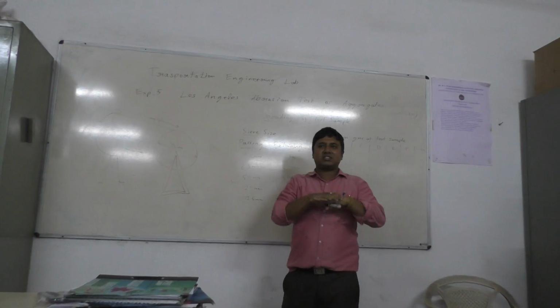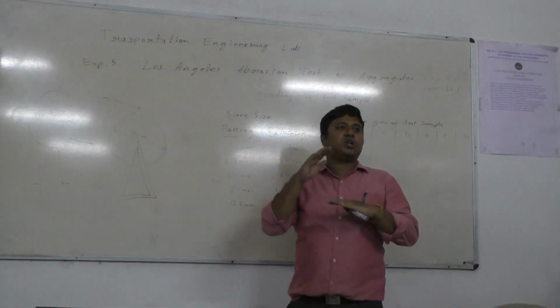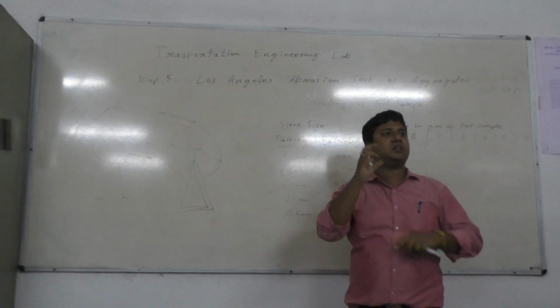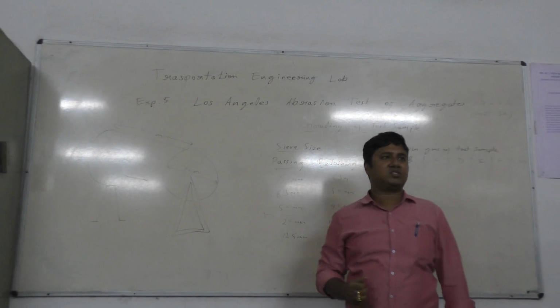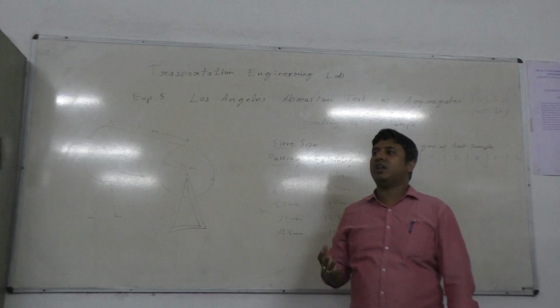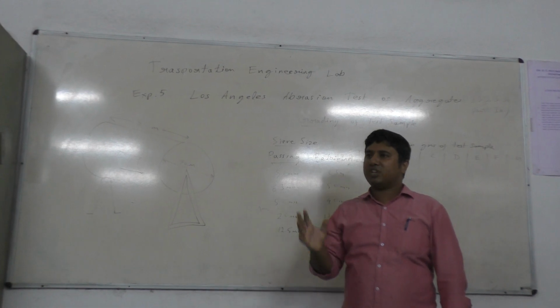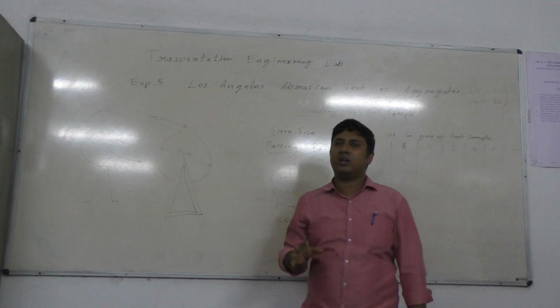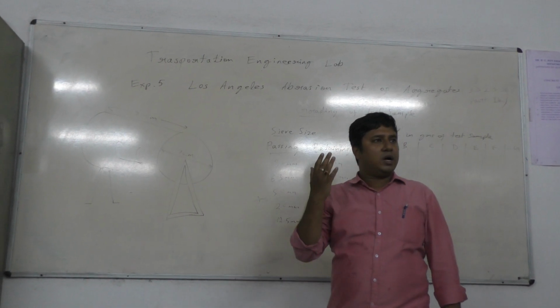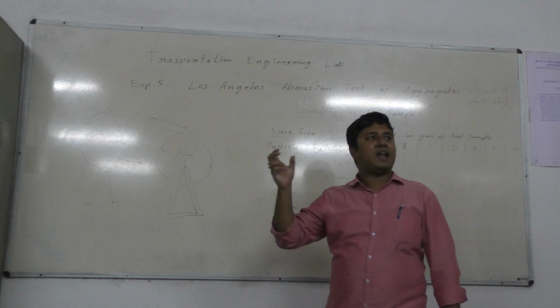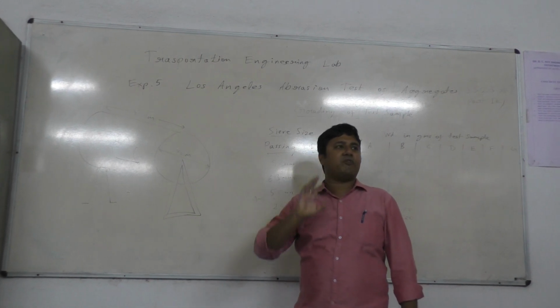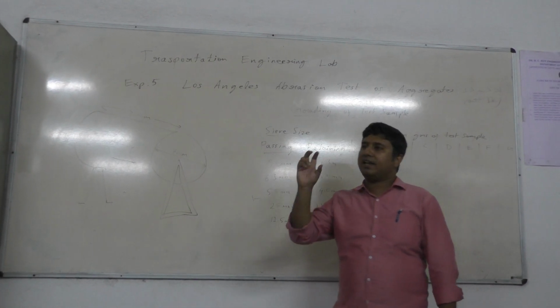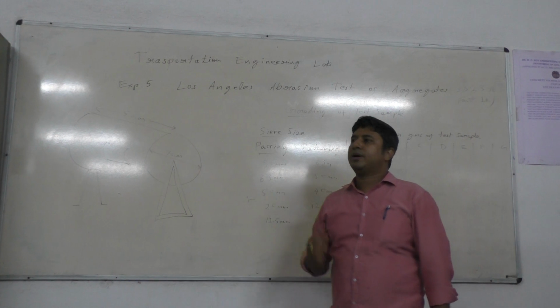So to test how much abrasive force the aggregate can carry, we perform this test. From this test we can judge how much abrasion the aggregate that has come as a sample for the construction of the pavement can carry, whether it is safe or not, whether the aggregate can carry the abrasive load completely or not.